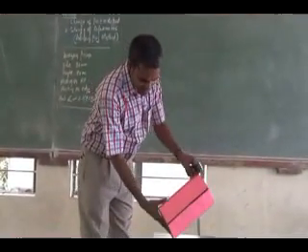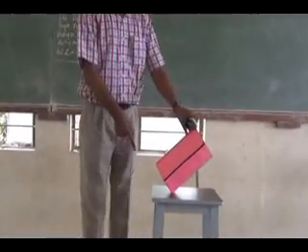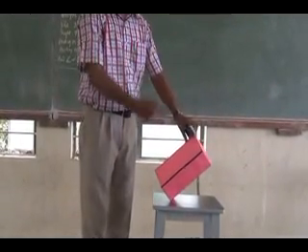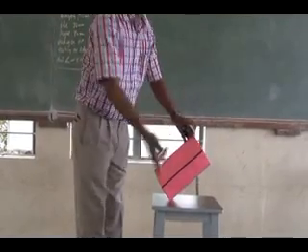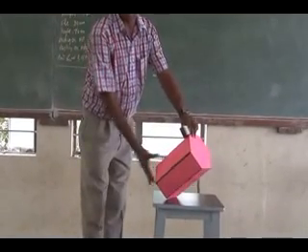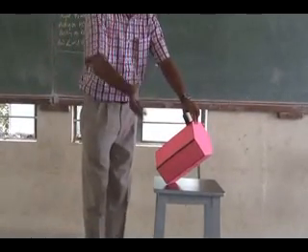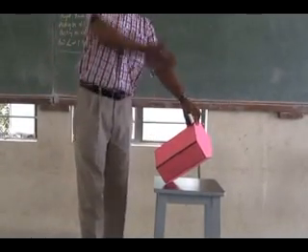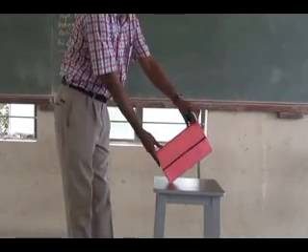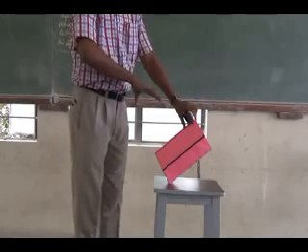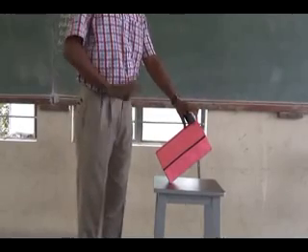So one of the base edges is resting on the ground and the axis is 30 degree inclined to HP. So it can be inclined like this. Another condition is given: the axis is inclined to HP as well as parallel to VP. It should be like this only. You know how the front view and the top view will be, you have to draw it.